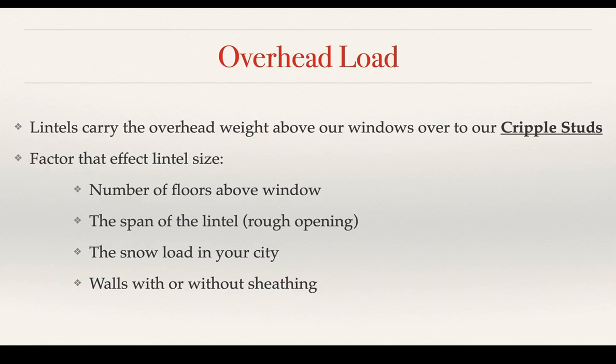So also, something that affects the size of the lintel is how far does it have to span. So we know that from when we're sizing floor beams, the more weight we're carrying, we can't span quite as far, right? So we have to put more posts under our floor beams. So the rough opening from cripple stud to cripple stud is how far that lintel has to span. So that's going to matter. Obviously, a 2-foot window versus a 6-foot window is going to make a big difference.